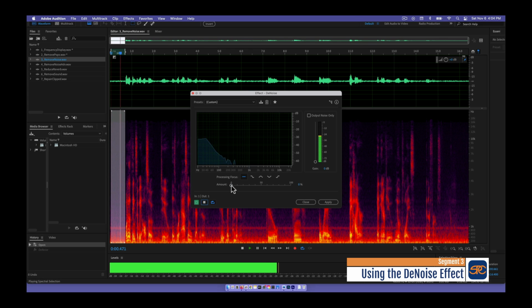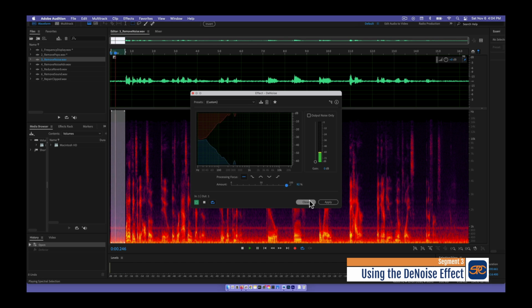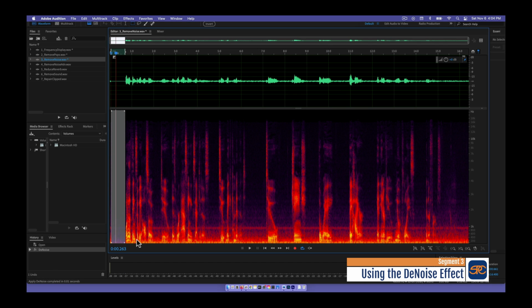And while it's playing, we're going to turn this up till we can't hear the noise of the fan anymore. We're having to turn it up pretty loud, almost pretty much to 92%. And then we're going to hit Apply. And we'll see, if we click away, that got rid of all of that.